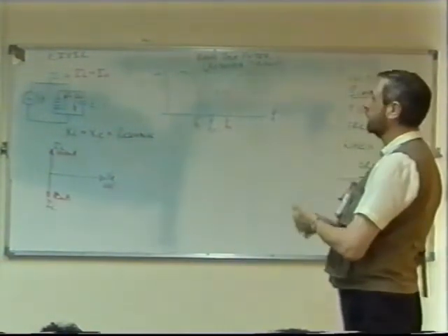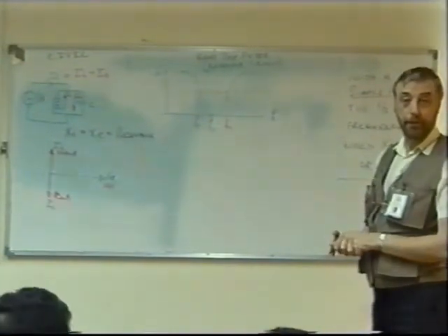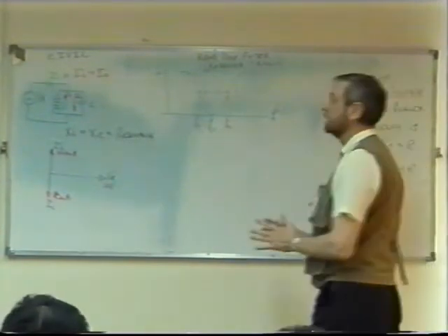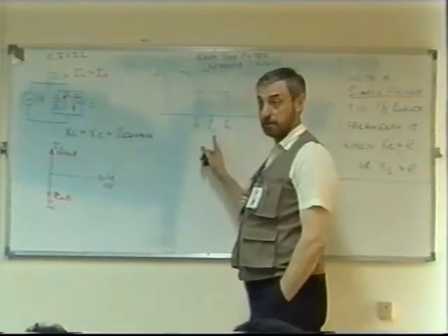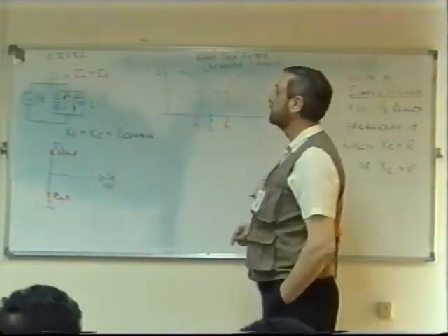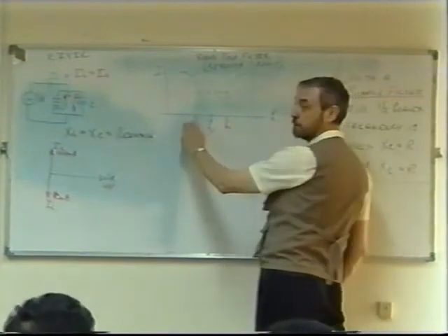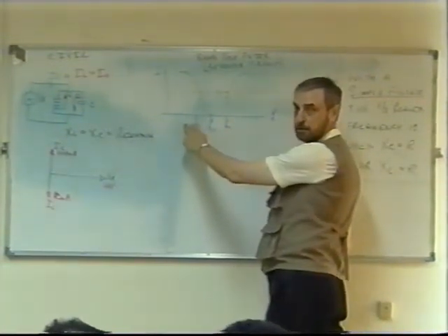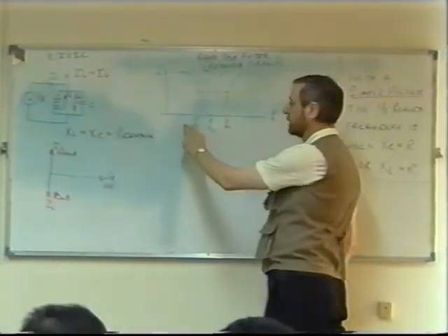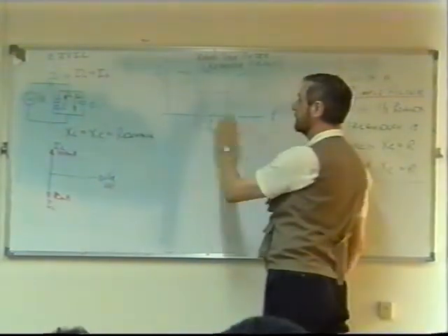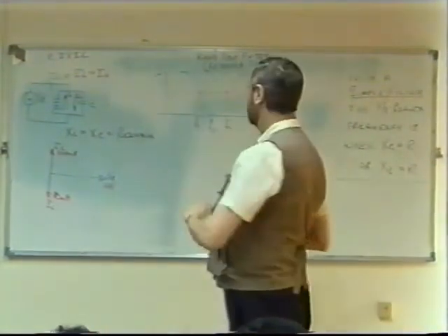So it does depend on how we connect our inductor and capacitor, whether we're using it as a band pass or a band stop filter. In both cases, XL equals XC at the resonant frequency. Now we have to see what type of filter it is, whether it's a band stop or a band pass. We have not calculated these two frequencies. That's a different calculation, it involves different things altogether. We don't actually do the calculation for these two half-power frequencies, not for complex circuits like this.